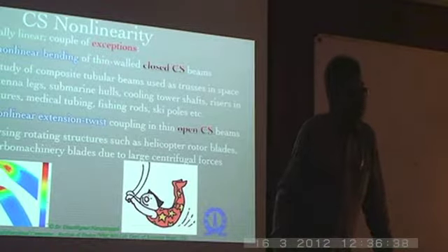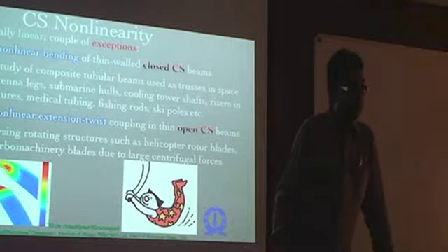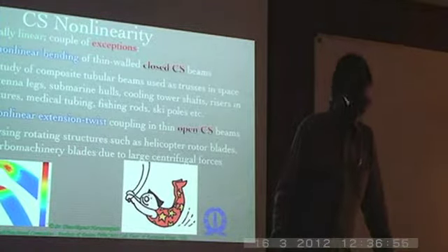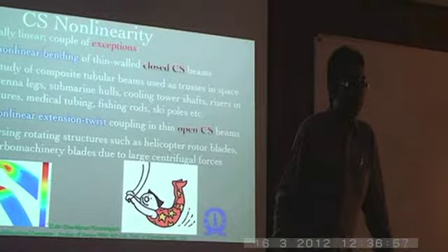Means we'll do the cross-section analysis between two spars, between two ribs. One cross-section, we'll take those properties, whatever two spars and whatever skin is there, full thickness, everything. Then we'll do the cross-section analysis. That's correct. We'll get the warpings and then the S matrix. That's right. Then only we'll see whether this thing is there. Exactly. Depending on loads. Exactly.